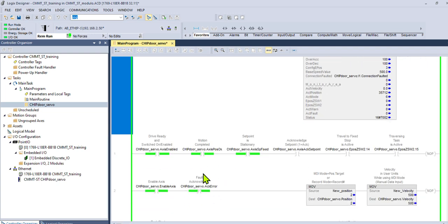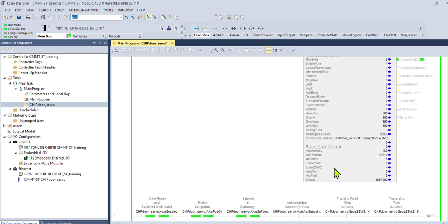I have a little code in here, so I had to turn off the fault acknowledge. So I'll change this to a 1, and we got a 1 here. We have to execute or start the task, and it needs a toggle here, so I need to go from 0 to 1. It's looking for a 0 to 1 transition.